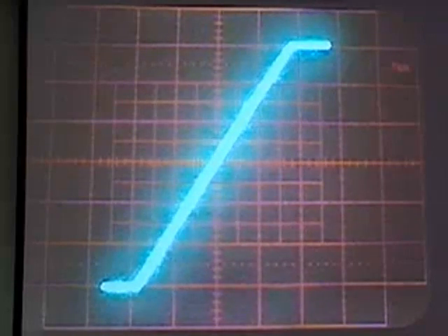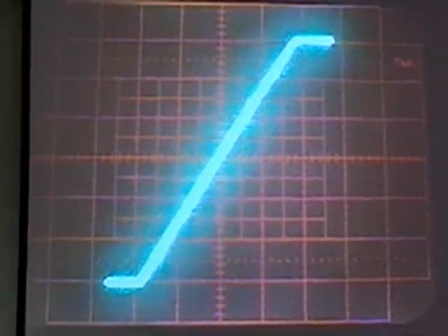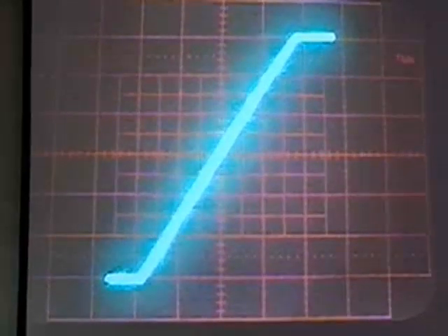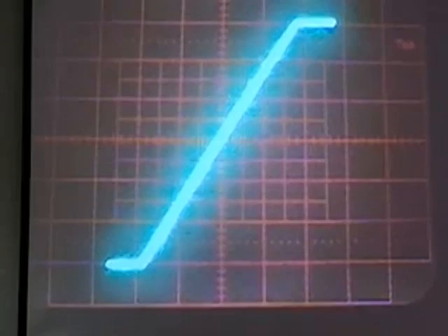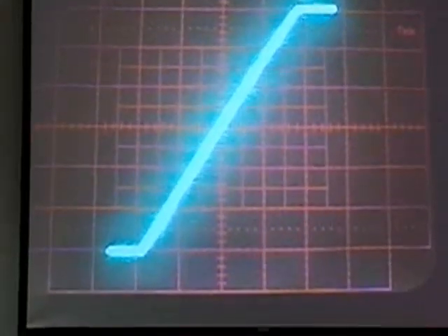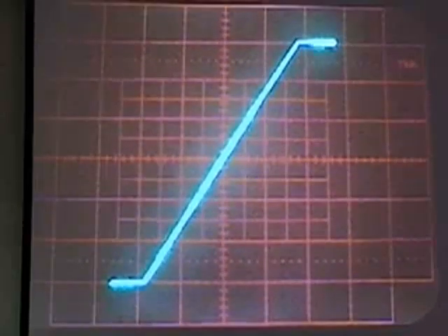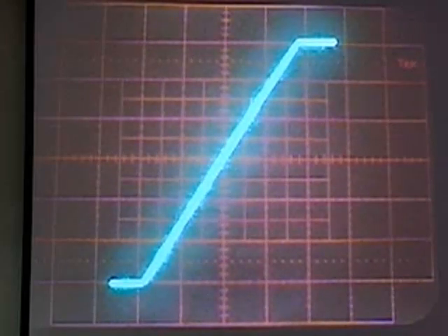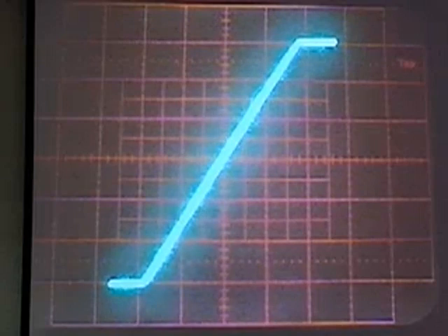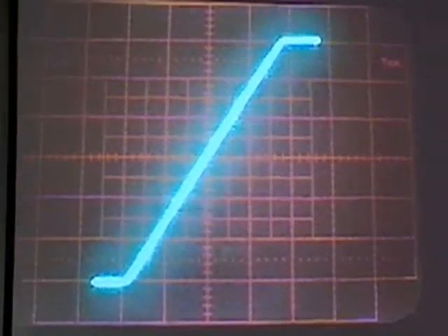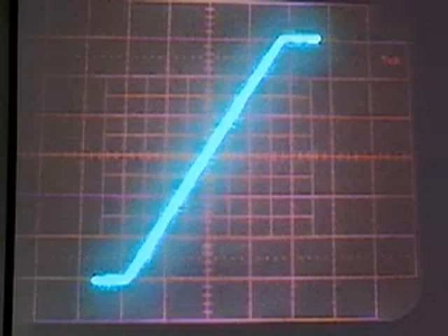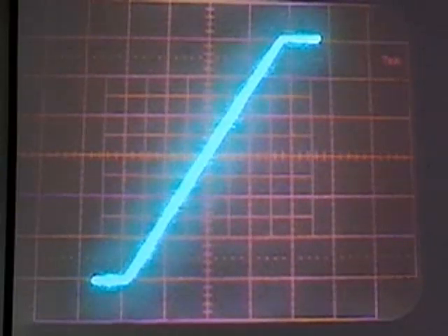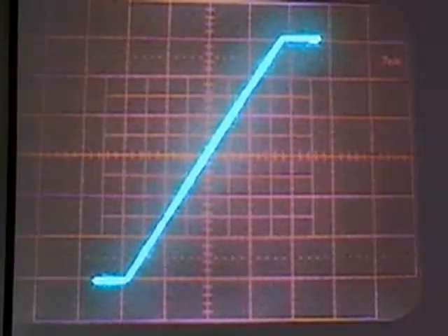So what I'm going to do now is heat the op amp to the wazoo, and this isn't going to change, because it's my external resistors that control it, independent of the value of A, provided A continues to be very large. I'm just articulating the V out, V in curve. Let me start heating the op amp. Notice that it's pretty stable. It doesn't change because it's independent of the amplifier values.